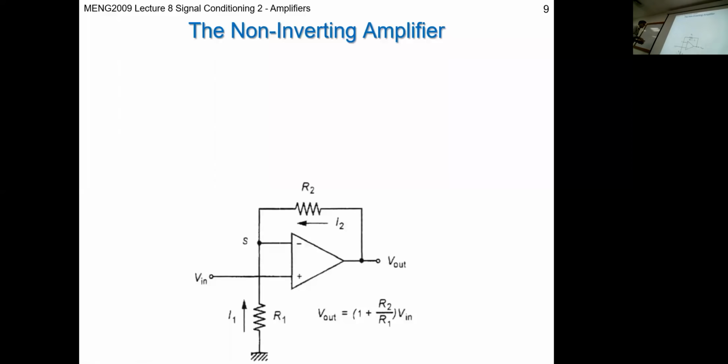All right, so we have to determine the voltage at point S here. What rule are we going to use to determine that voltage? Well, if we look at the circuit from here, you've got an output voltage, and it passes through one resistor to the voltage we're interested in, then it passes through another resistor to ground.